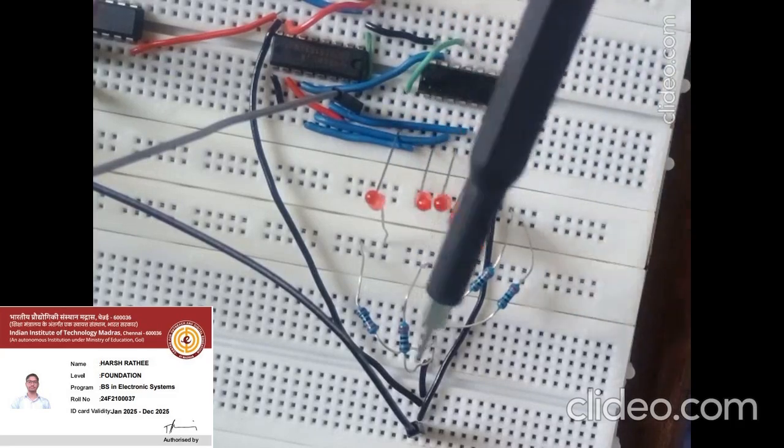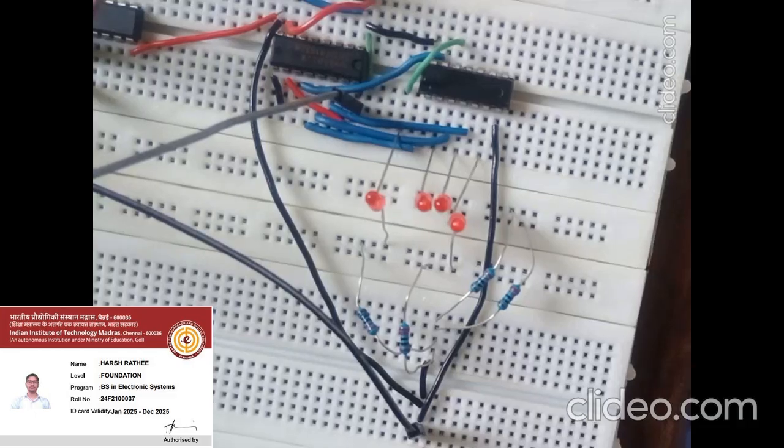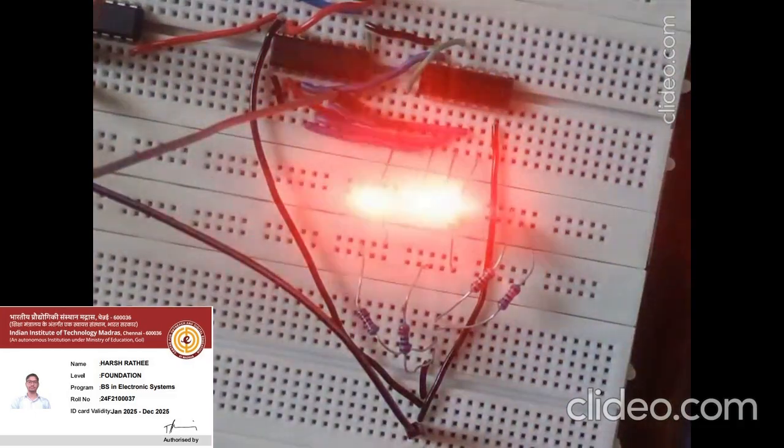These pins are connected to resistors, and resistors then further to ground. We also connected the ground terminal to ground and VCC to 5 volt of this 74LS04 IC. Now we provide a square wave as earlier and record the output. Now we have provided the square wave of 5 volt at 10 Hz frequency, and this is our output.